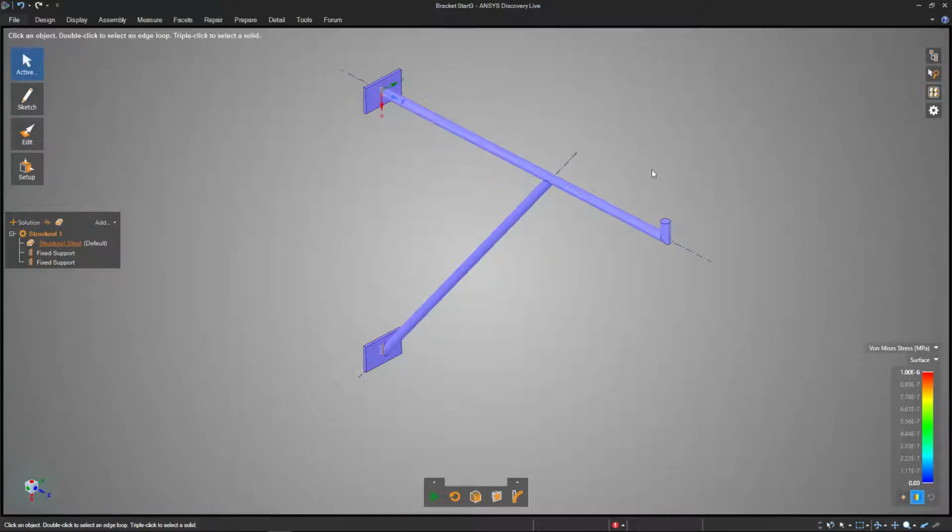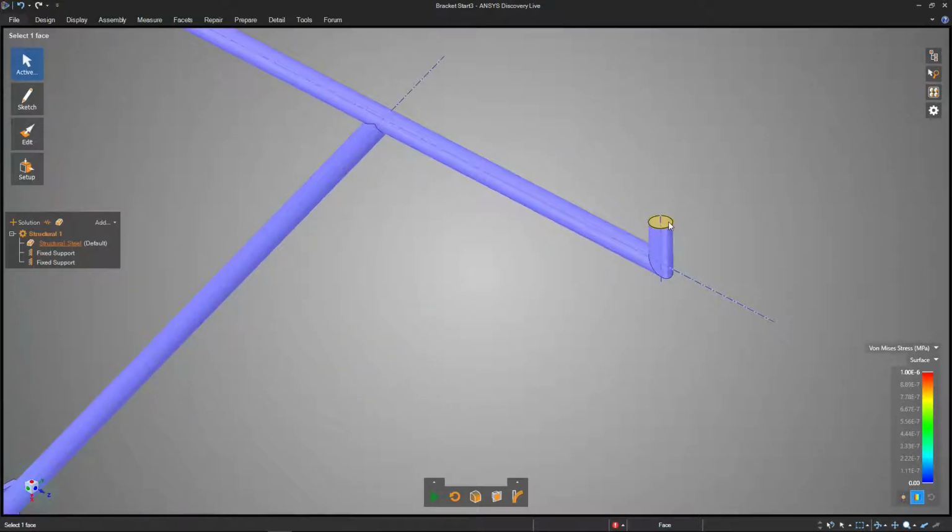So I'm going to escape from there. If I click on this cylindrical face here, it's going to keep that force right in the center of this circle, and I can make sure that it's normal to the surface by default, so it's going to be going straight down. So new force there. For my students, I tell them to use 186 newtons because that's the value that we're using to actually test their fabricated final products. It's the weight of a 5-gallon bucket full of water. Default units here are newtons, so you don't have to explicitly put the N on there, but if you do, it's not going to hurt anything. Once I hit enter, it commits that.